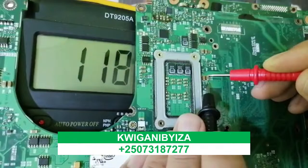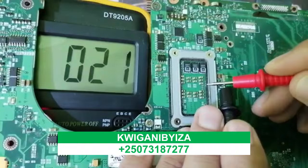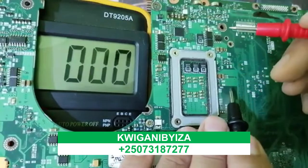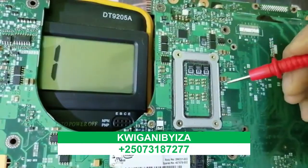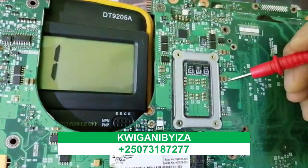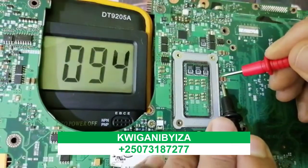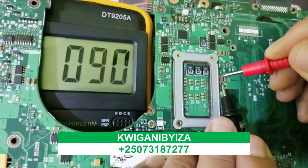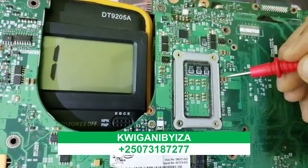We get a reading here in the multimeter. We should not get a reading like this, a 0 in the multimeter. If we get a reading like this, it means the capacitor is shorted. Okay, so let's check the second one over here. Okay, we have the same reading here. So these capacitors are good.